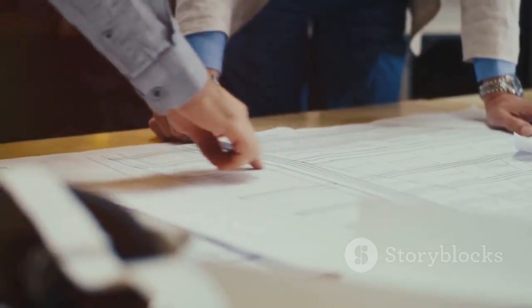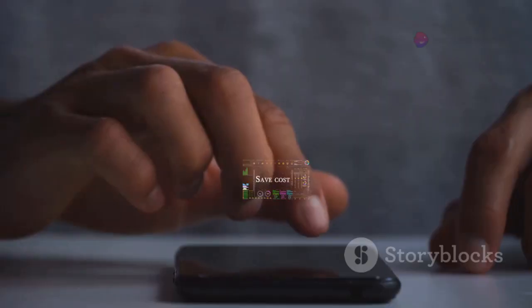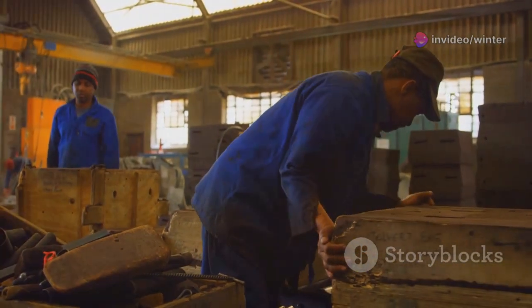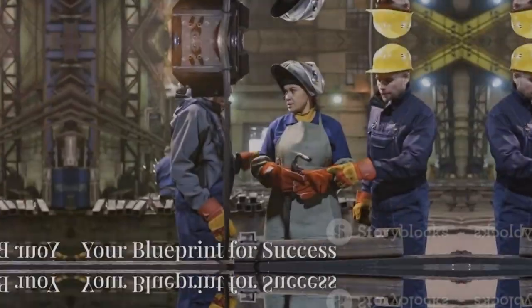Plan for future changes by making likely to fail or update features into inserts. This flexibility saves time and money over the mold's life. Think like a maintenance tech, design for easy service. Smart planning upfront pays off for years.